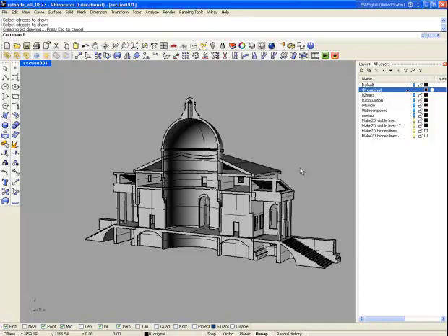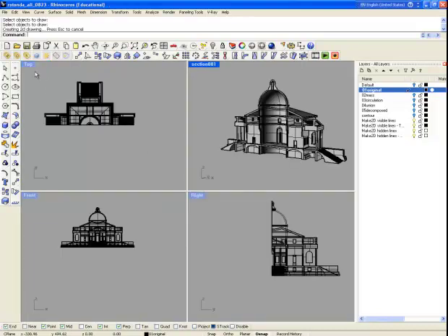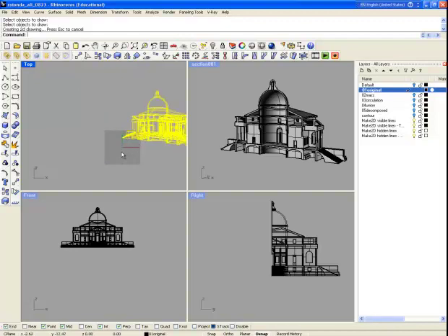Right? So now your outline of these drawings with hidden lines is already laid out in the top viewport. So you cannot see it over here. So click Viewport and then Top view. All the generated two-dimensional drawings will be made around coordinate 0, 0, 0. So what do I mean by coordinate 0, 0, 0? As you see, this is coordinate 0, 0, 0. So all the generated drawing will be made around over here.